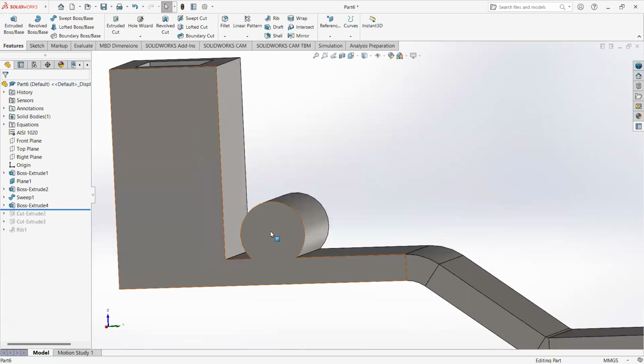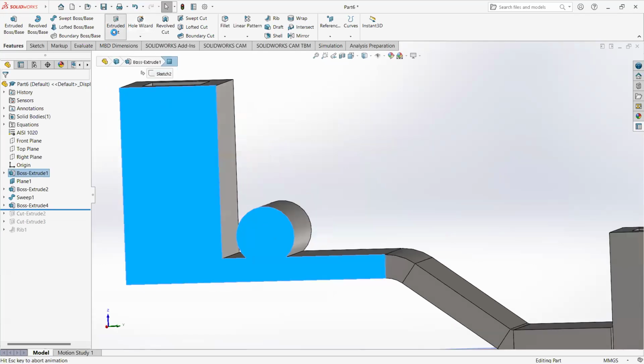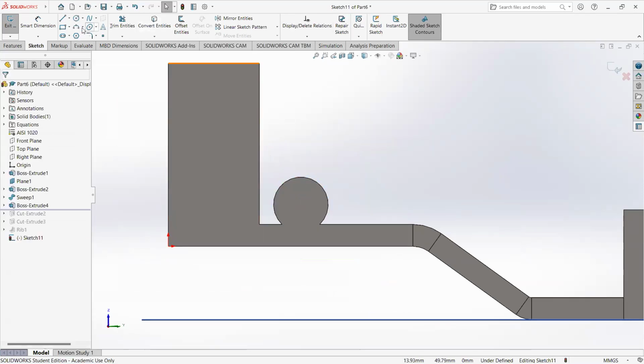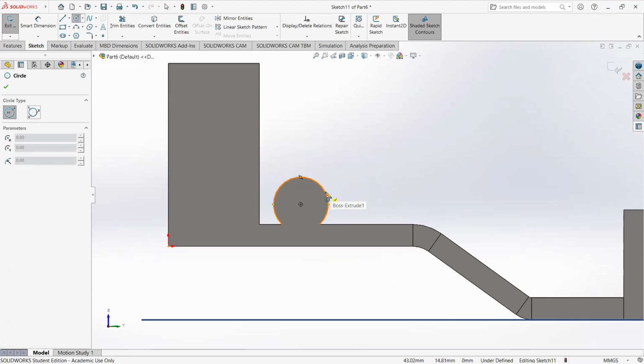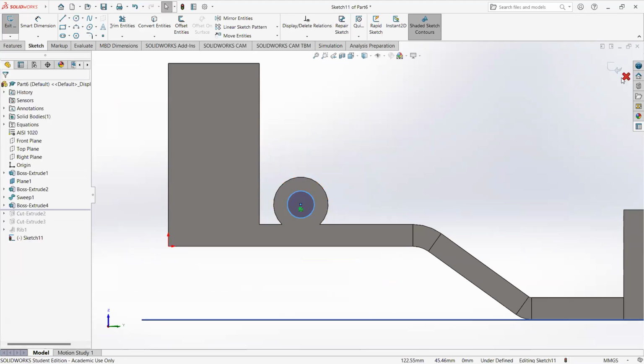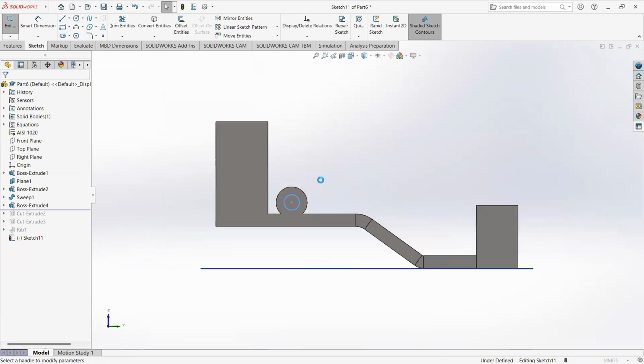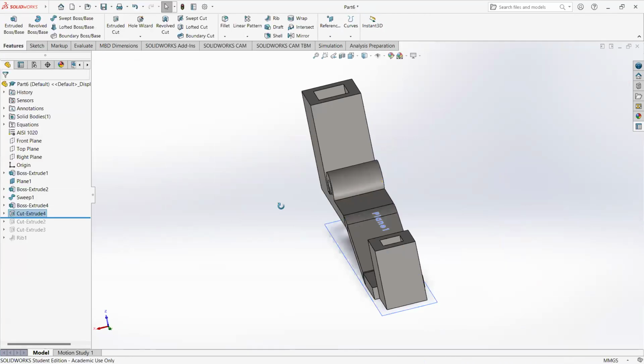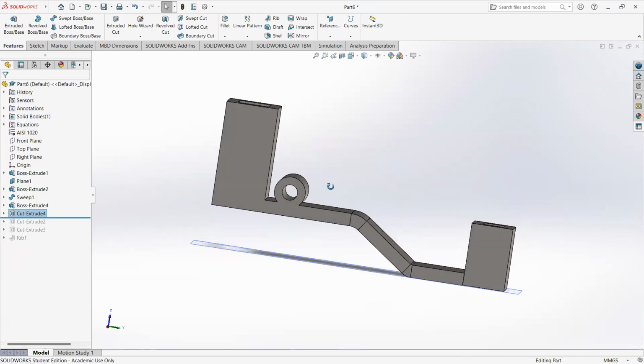So I'm going to also add the hole just with an extruded cut and a circle. And I didn't hit the center. Pay attention and hit the center. Just slow down, grab that, get the center. There we go. And again, I'm not constraining anything because really, I'm making it up on the fly anyway. I made up all these dimensions. So I've got my through hole.